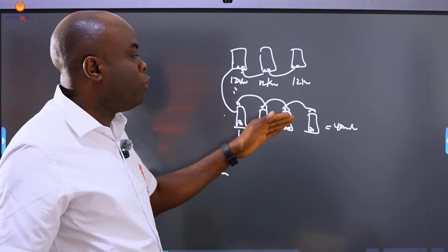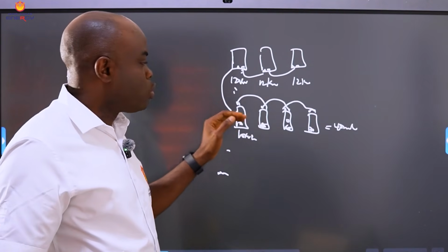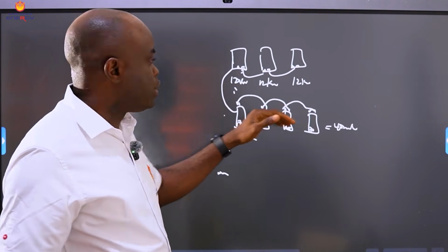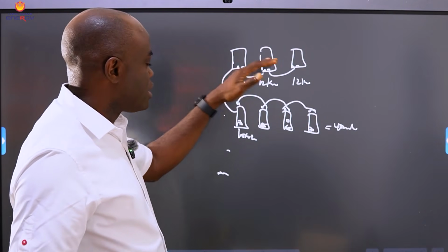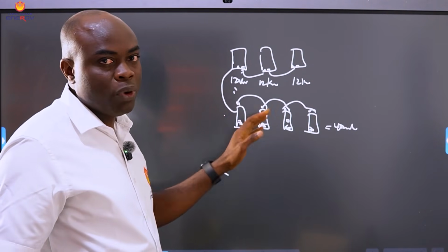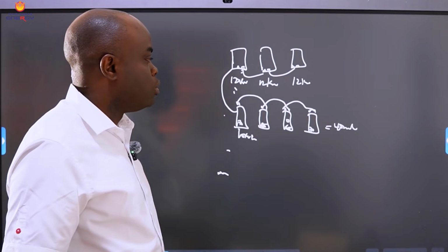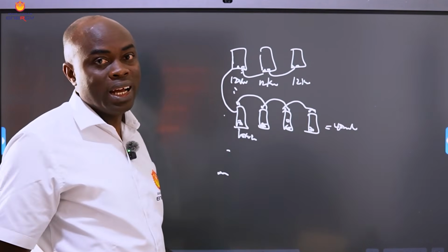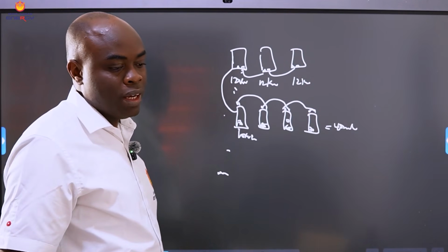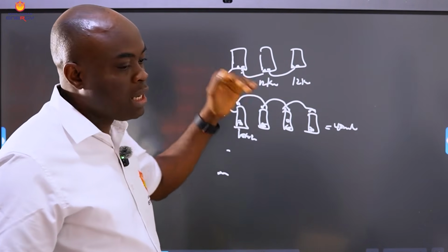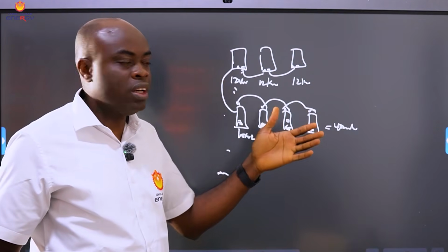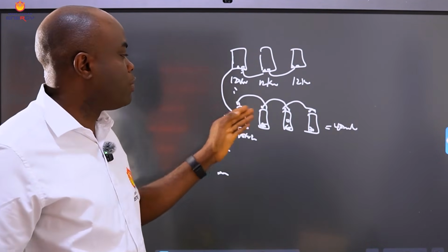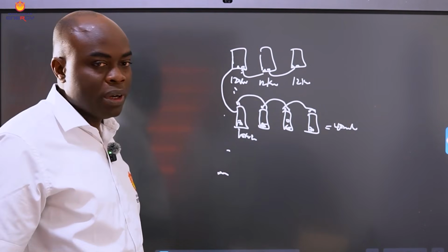And it can only happen using your communication cable. So without the communication cable properly plugged into the battery and also to the inverters, which helps them to communicate properly, then there will be an issue. Also, you know that if it's not there, the inverter will keep showing an alarm or keep giving an error signal. There will be a fault signal continuously, because it's a protection over your system for the longevity of your system and also for its performance.